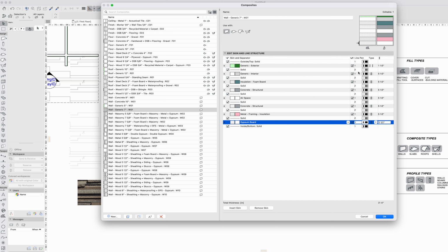We have the pen types. So that's the line pen, the end pen. You can see hopefully here, we see the butt end of that. That can also be turned off. The line pen rather can be turned off, or the butt end line can be turned off, so you can have a totally open-ended. Something like that we might want is to not show the end line at the airspace, for example. Let's just say that airspace is 5 inches. The concrete is 8 inches on each side of that.